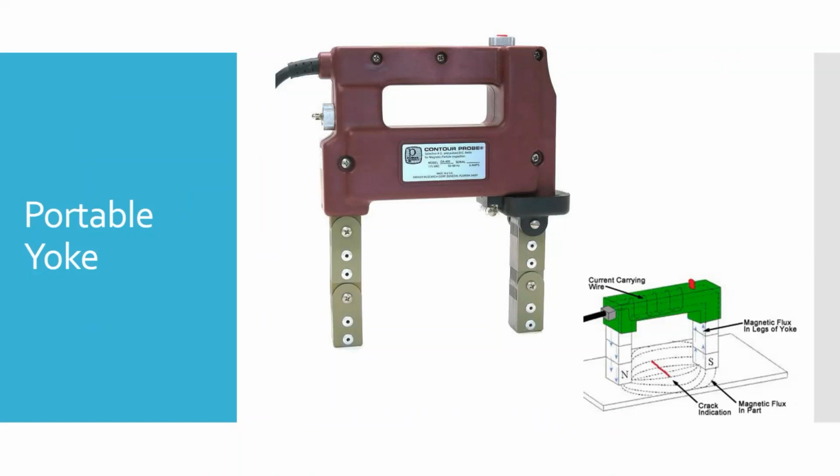These do have another use as well. When we get to the end, we'll talk about demagnetization. We've got to demagnetize our parts. When we had airplanes that got hit by lightning, part of the lightning inspection is making sure nothing got turned magnetic on the airplane. We'd have to go around with a Gauss gauge, same one we use in the lab, and check parts, particularly steel parts. So things like landing gear legs, the window frames around the windshield, especially because the whiskey compass is behind it. Fasteners, all your little screws, right? Most of those are steel, even if they're in aluminum.